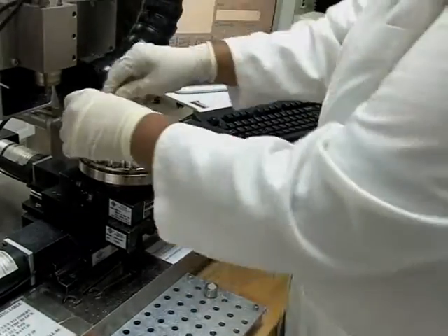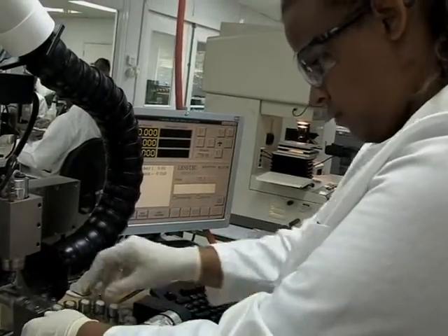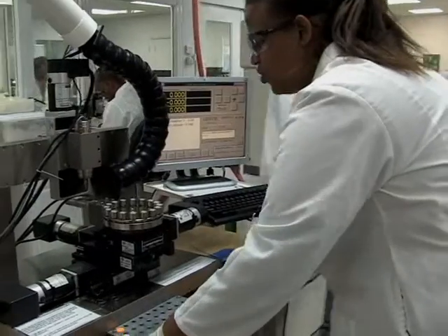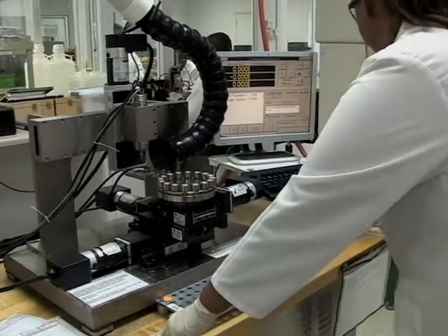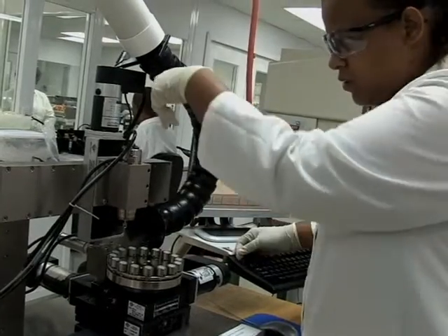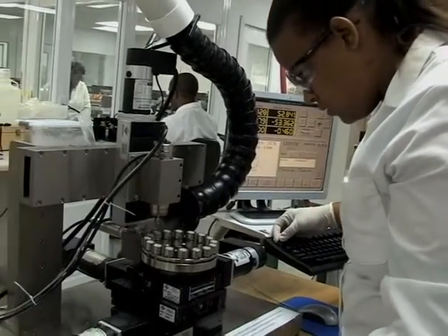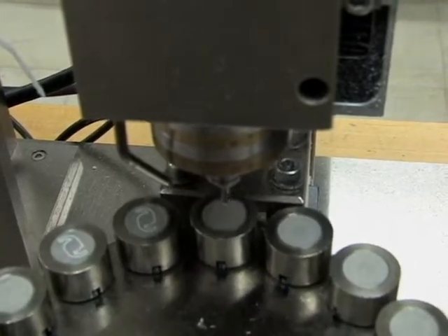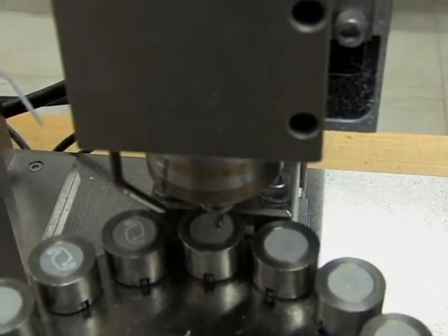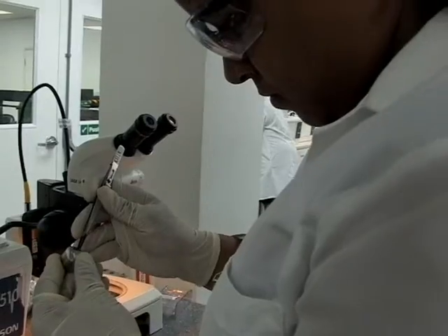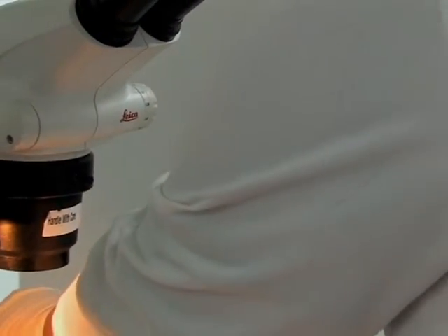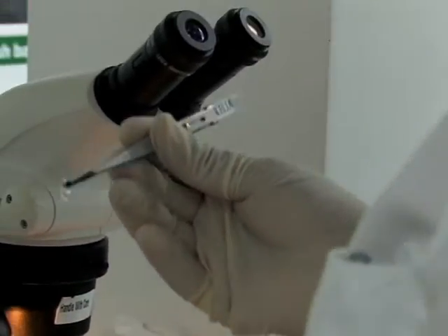After the convex side has been cut, the milling process takes place. Basically, the milling process is another preset program in the computer where the actual shape of the lens is cut out. As you can see, the technician will check the specification sheet for the particular model once again and load the corresponding program. Once this lens has been set to cut and is completed, the technician removes the block from the table and checks that the lens is within specification or within the tolerance range.